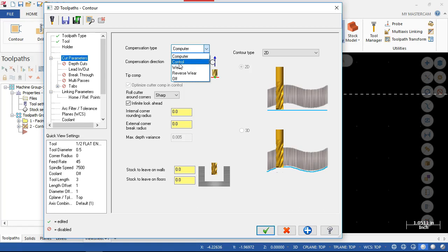It's also going to have to follow the rules of compensation that say you need the radius of the tool to engage compensation, or for compensation to engage properly. And then if the tool can't move through that arc, it's also going to flash the compensation error that says the tool is too big to cut that arc, just like if we were manually programming at the control.